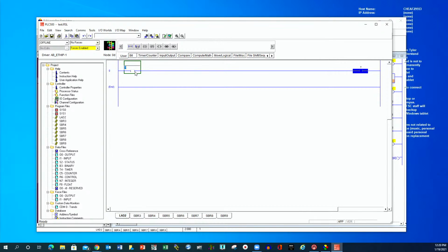You can also create something called a never false information, which is called an NFI. This is not advised either. Basically, you create a bogus bit. So let me make one: B3:10/0. It's just some random bit that is not being used by anything.